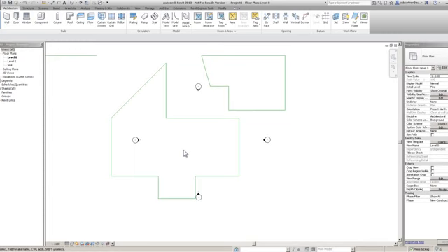Now, when you've got a chain of anything, in this case we've got model lines, but this can be the same for pipes, walls, boundary lines, lots and lots of different things. Whenever we've got anything that has been drawn in a chain and they're joined at the end, this works like this. If I hover over one of those lines or walls or pipes or ducts, anything that is part of a chain, and I simply hit my tab button, don't hold it down.